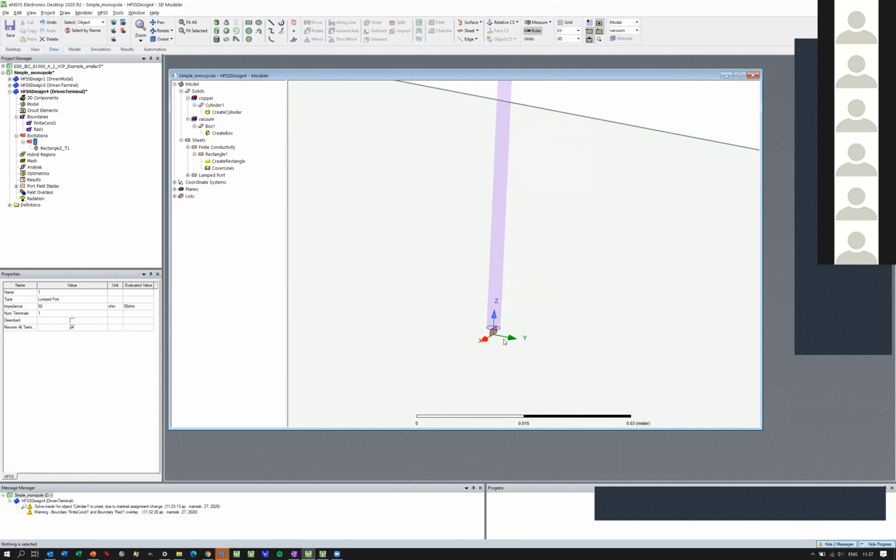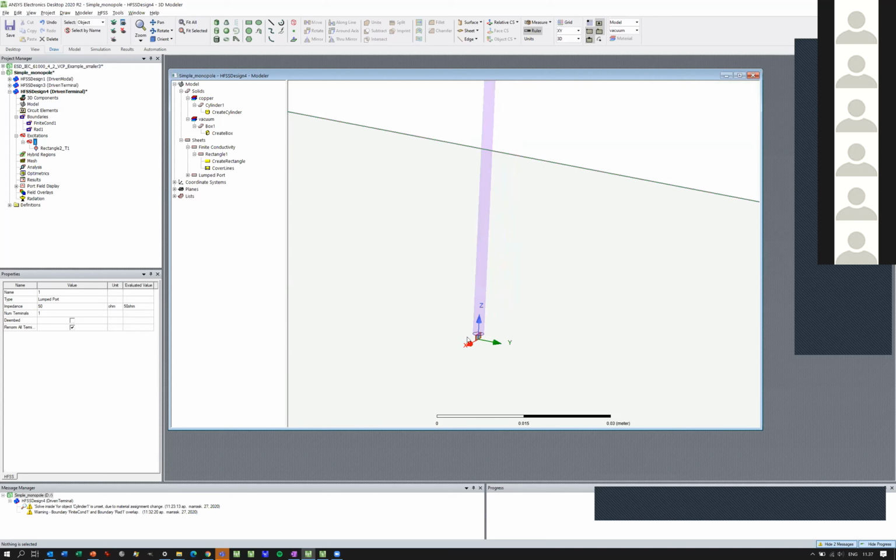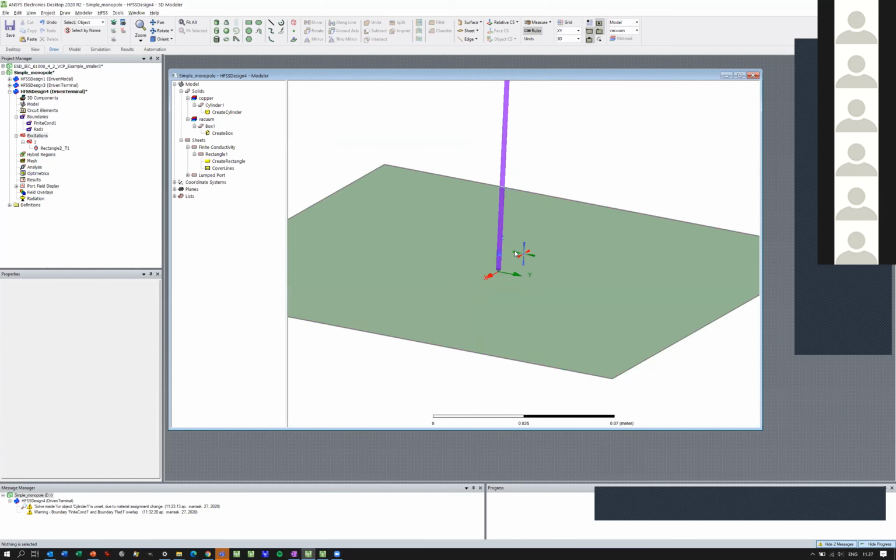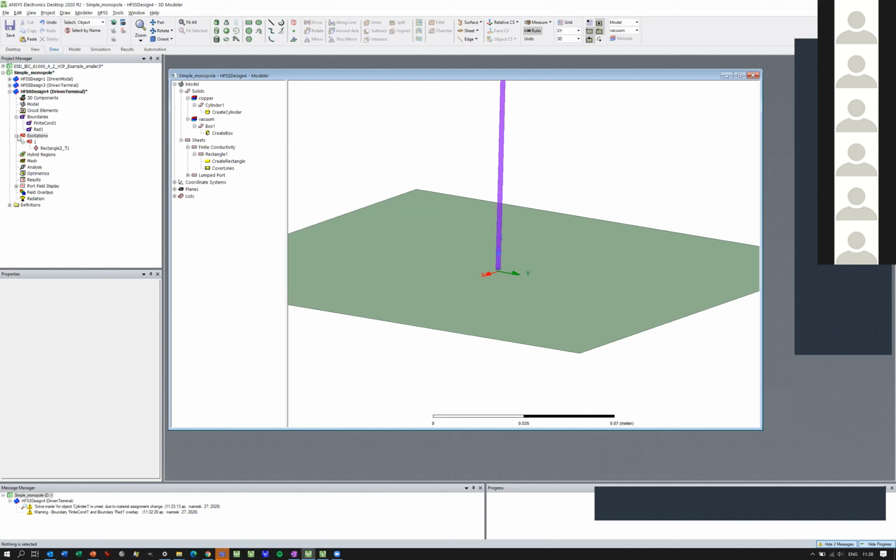So that means that this is my reference, this is my kind of antenna element here. And this is the way the power, or voltage in this case, will come inside. So what's still missing is hybrid regions, which we will step over. As I said on Wednesday, meshing is more or less automated. We can do some manual meshing here, but I'm skipping that because I will just use the automation.